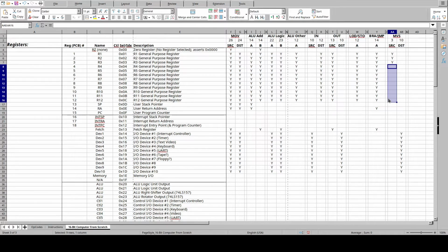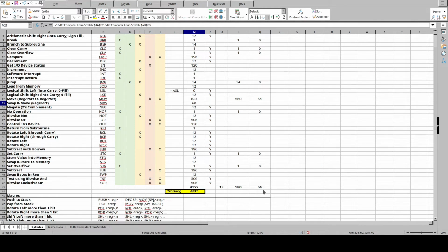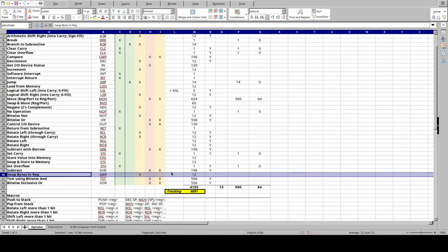But again, that's going to be quite the number of instructions. So I'll have to take a look and see what I can reclaim here and if I can make enough room to fit any more of those instructions. Right now, I'm going to have to be very judicious about that. Is it the end of the world? No, because I can move things into a register and then I still have the swap bytes in register instruction. It just is going to take 2 instructions to perform the same operation.